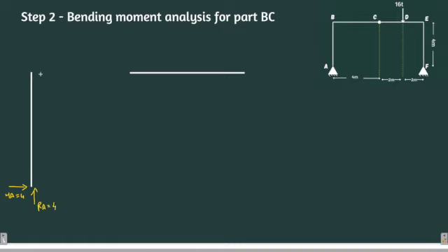So to counter these two, I have drawn HB, which was 4, and RB in the opposite direction, which was again 4. Right? Now, as previously explained, there was a clockwise moment, MB, of 16 units. Now we have to analyze BC. So for BC, this is point B and this is point C. I'll just draw the equal and opposite forces and moments as here.